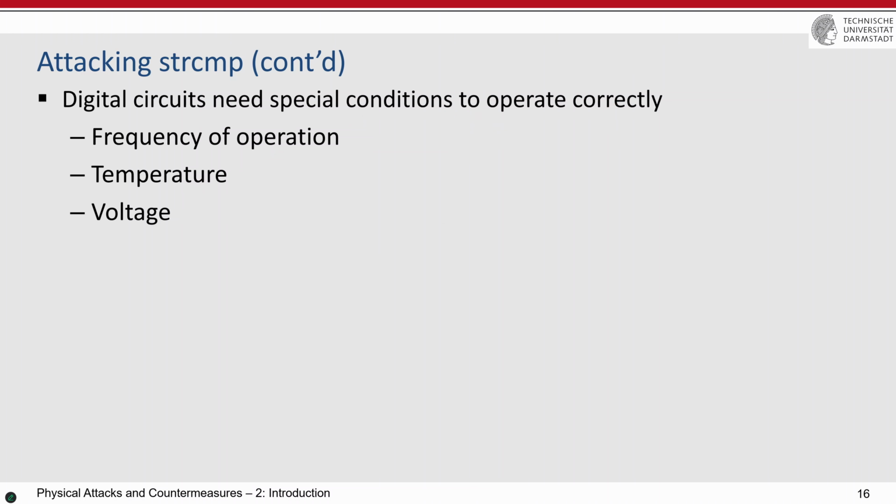They may work, for example, at maximum at 80 degrees. If you bring them to, for example, an environment which is 100 degrees, what happens? It affects, again, the delay of the combinational circuit. And then if you keep the clock the same as before, then again, the time might not be enough for the combinational circuit to work appropriately. And again, the result might be faulty.